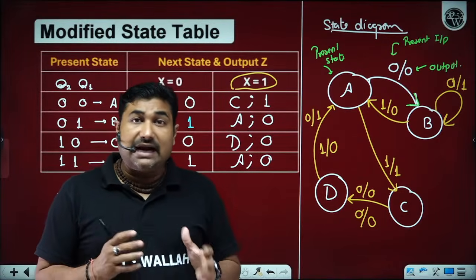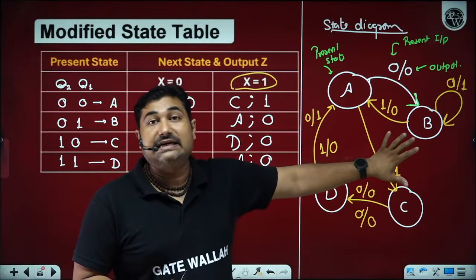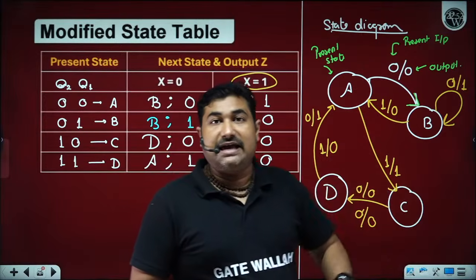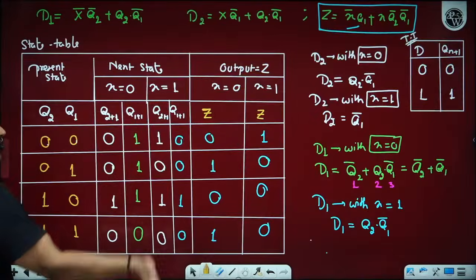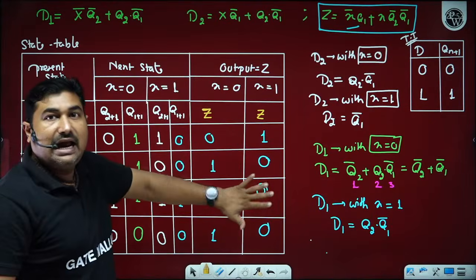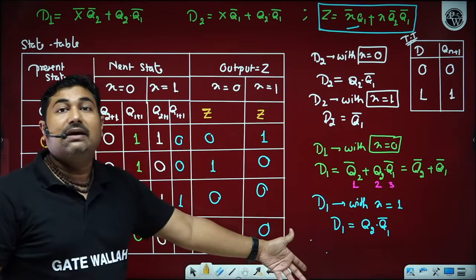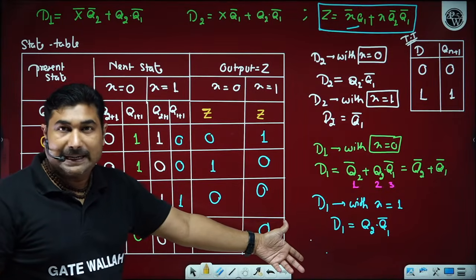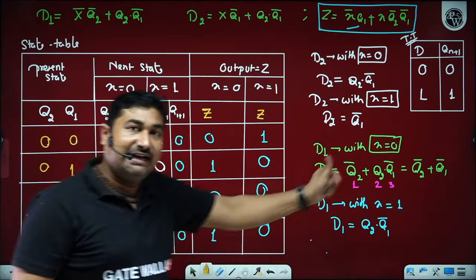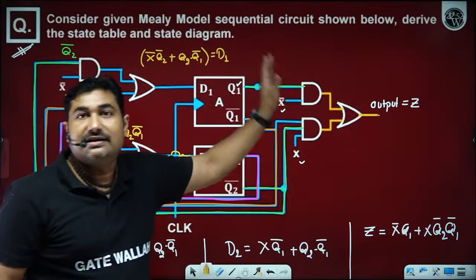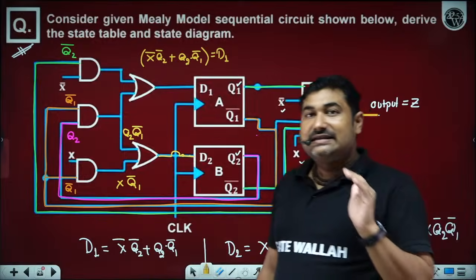To design any desired state machine, first of all, we understand the user desire and construct a state diagram. After this state diagram, we can construct a state table. This state table is extended into an excitation table for the flip-flop with which we want to design. Then we write the excitation equation, minimize it, and implement our desired circuit. So this is the process to design any desired state machine.